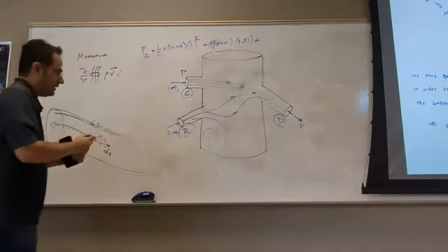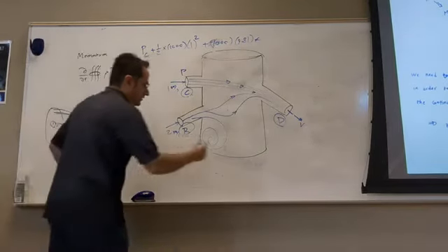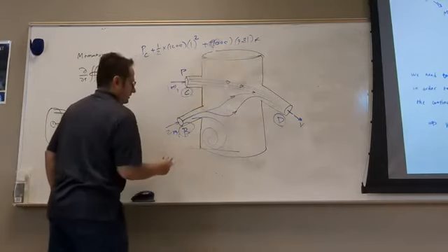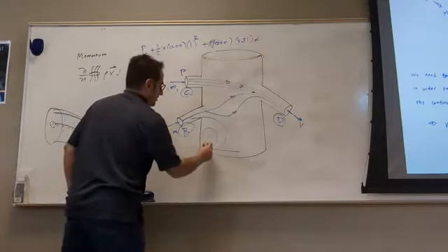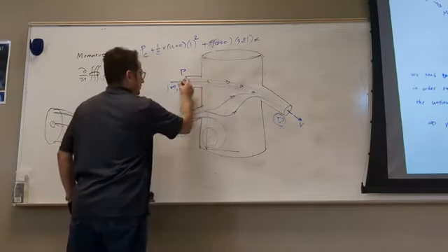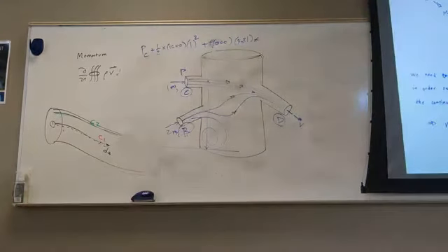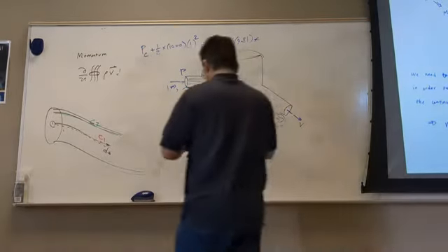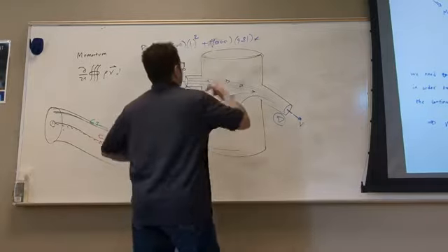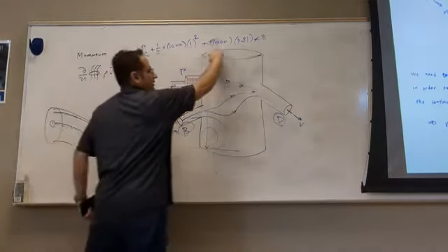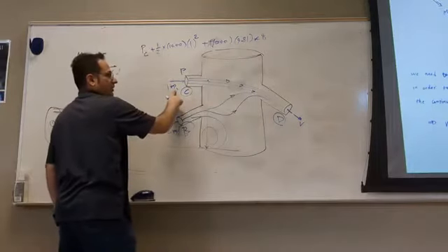So for Z, you can take a reference, it doesn't really matter, from the bottom or top. I take the reference from the bottom. So Z is the elevation of this midpoint there. And according to the figure, that distance is, if the entire thing is 10, minus 2 is 8. So you put 8 here, times 8. So this is the sum of Bernoulli from point 1, C.